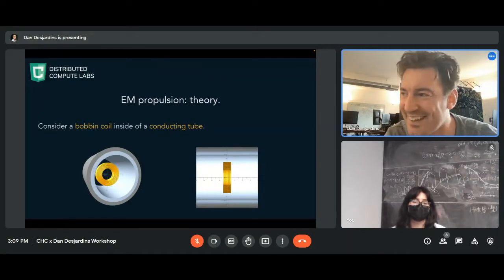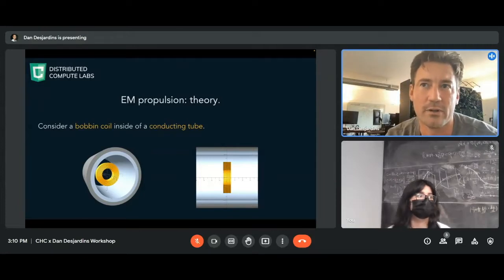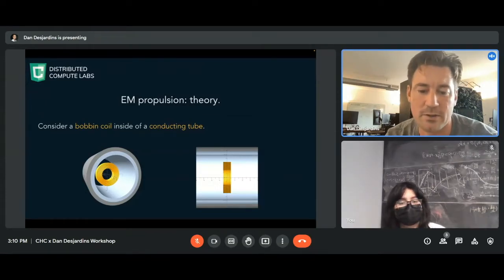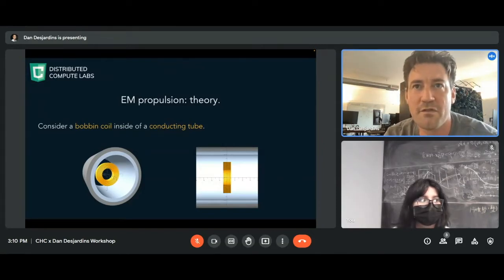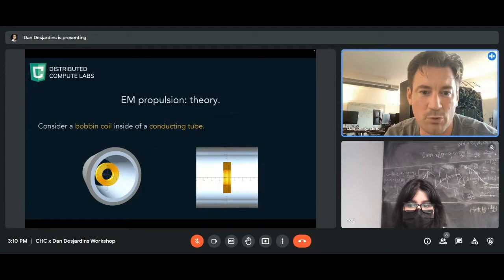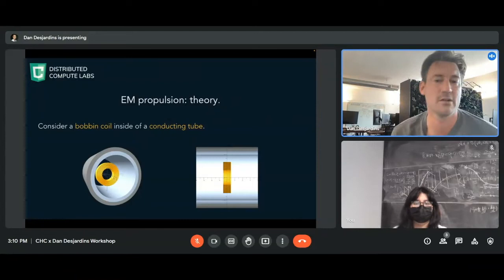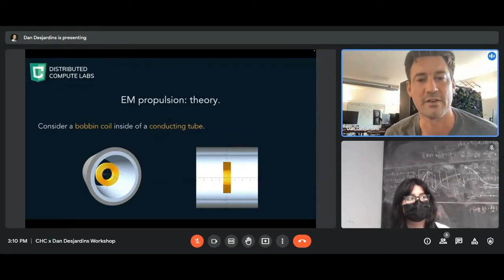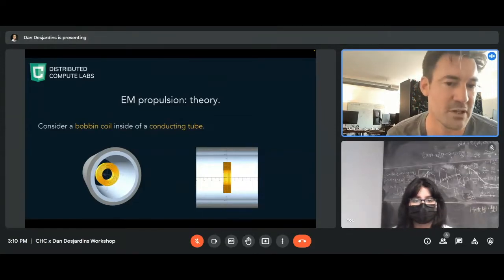Now, everyone here, if you remember your electromag courses, if you've taken a little bit of that, you should have, I think, in your core curriculum, you'll know that conductors will, if you put a changing magnetic field near them, you'll induce eddy currents, via induction. And Maxwell's equations describe that. But if you have ferromagnetic materials, that magnetic field will also magnetize those materials and will enhance magnetic flux. And if you enhance flux, you're also magnifying the induced currents. That's getting quite complicated. So when you have steel, ferromagnetic conducting steel, you have simultaneous magnetization and eddy current induction effects. And those enhance and focus flux, and all that creates feedback back on the loop.